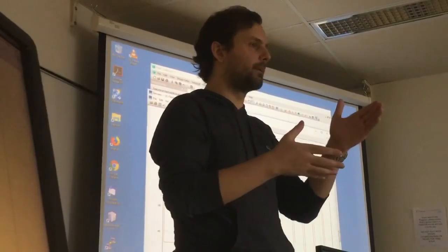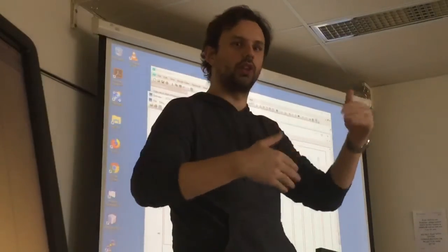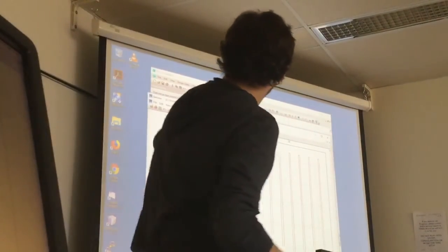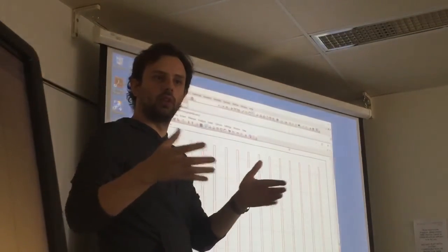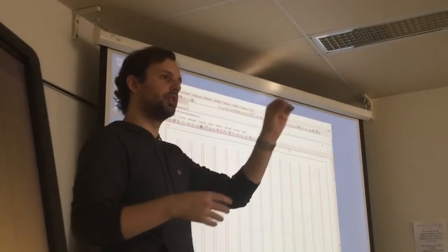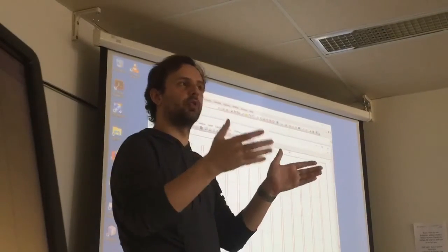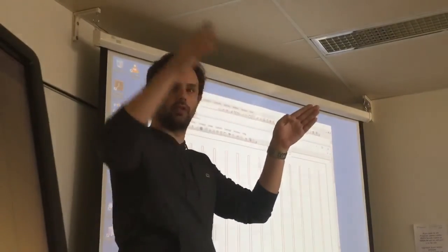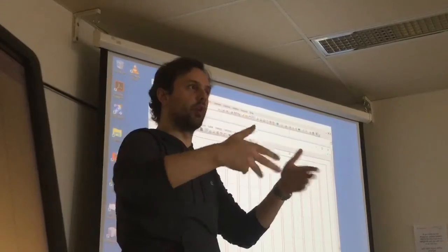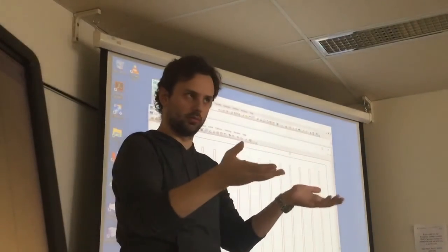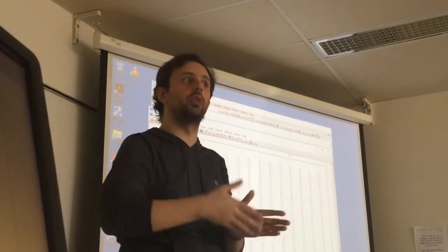So we need to be able to see all of these repetitions, like the switching. I told you it's good to take like 100 points for each one, because then the software will take 100 points for each repetition. Let's imagine you have a sine wave. If you have 5 points to do your sine wave, you have 1, 2, 3, 4, 5. Basically you have a triangular wave. When you have more points, you get closer to the sine wave, right? But if you add a lot of points, your simulation will take a lot of time.